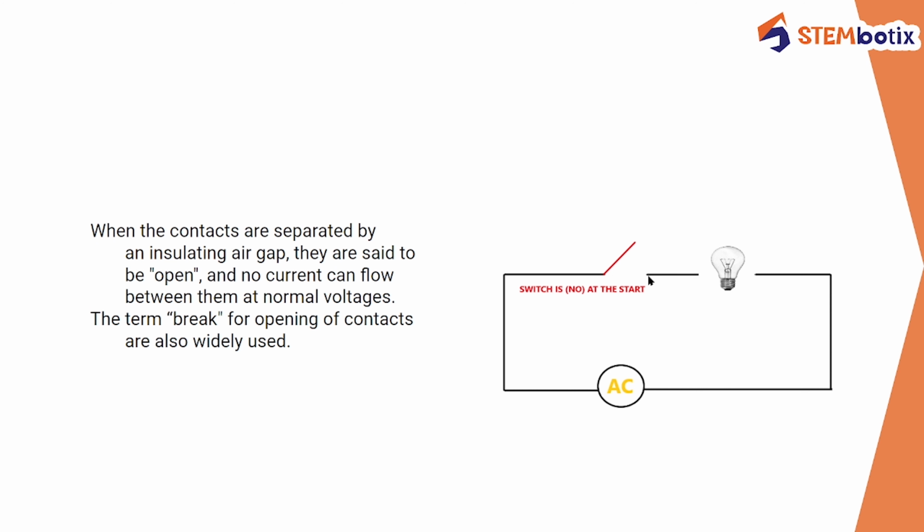So after operating it manually, they will turn on or turn off the circuit connected to it. So this require manual contact with the switch for operation and are classified into various different types depending upon the poles. Poles means number of input circuit available to the switch, and throws means number of paths for the flow of current available to the switch. So these are the main two types of switches, electrical and mechanical. So we will see first mechanical switches.